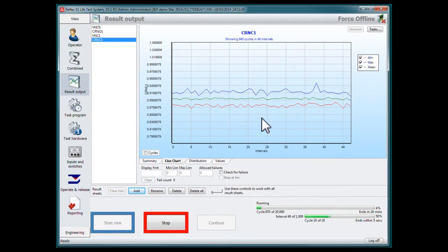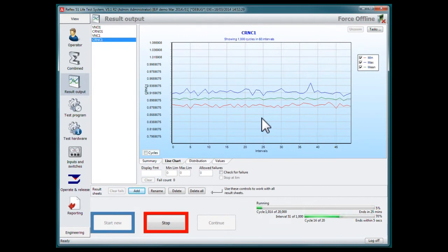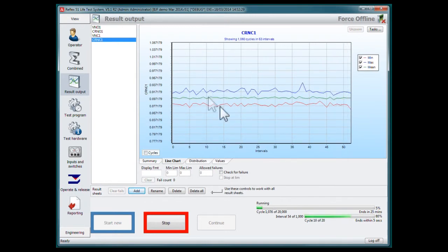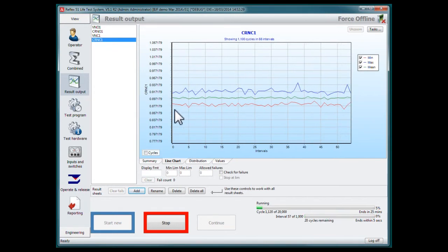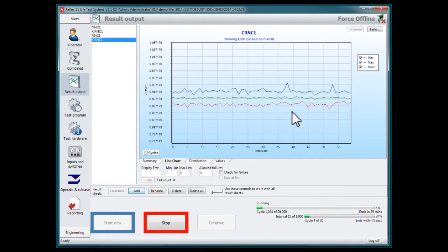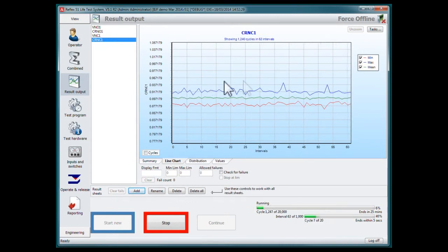And as a result, applied relay testing is able to offer a life testing solution that generates life test duration charts for not only voltages and currents across and through the contacts, but also timing information and operate and release voltage information that can be overlaid throughout that lifetime.